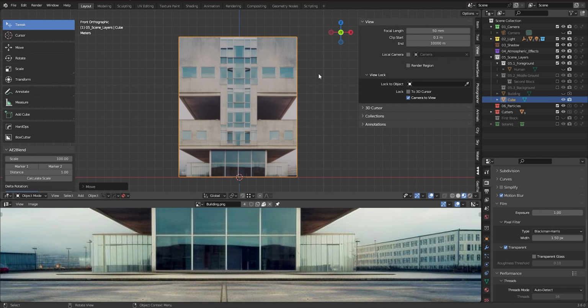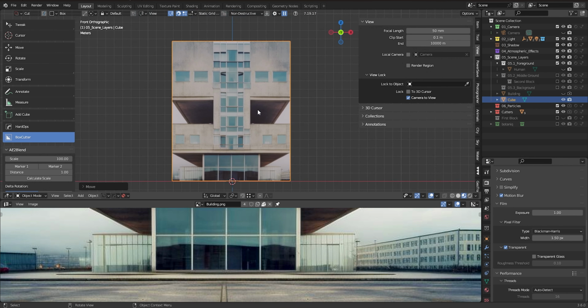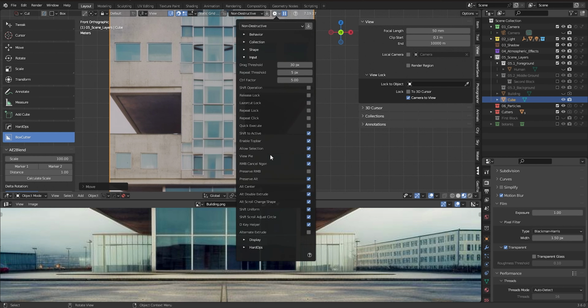Remember how we saw in the drawing itself how we're going to tackle this. So basically I'm thinking about larger details and then smaller details, cuts and everything after. This way we make sure that we don't have more geometry or more lines cutting in our object than we need, and also that we can solve things faster and avoid a lot of mistakes. So first thing that I'm going to do here on BoxCutter, Alt W, I'll press D here. For this to be available to you, it's like this D key helper, just make sure it's enabled.